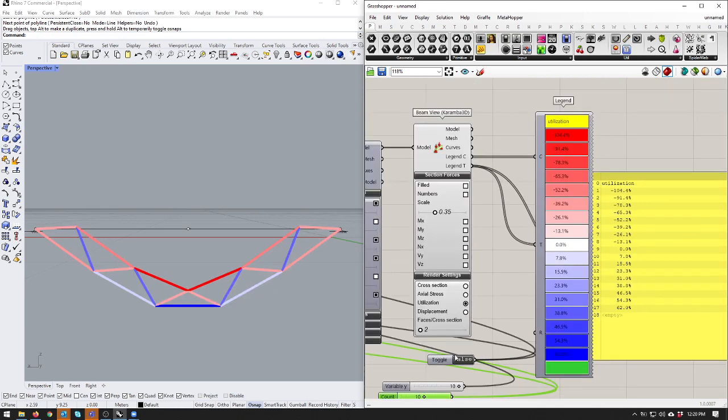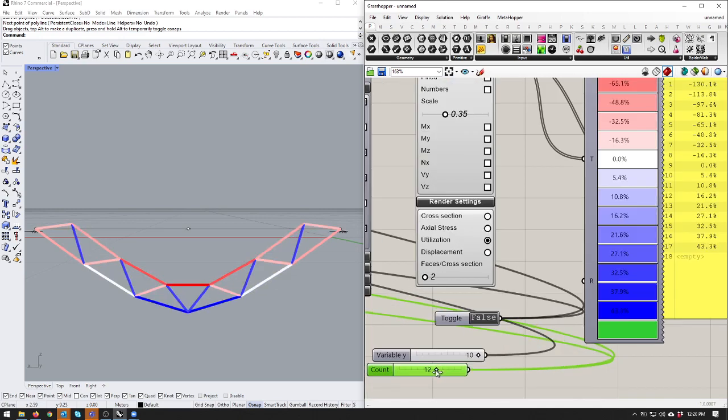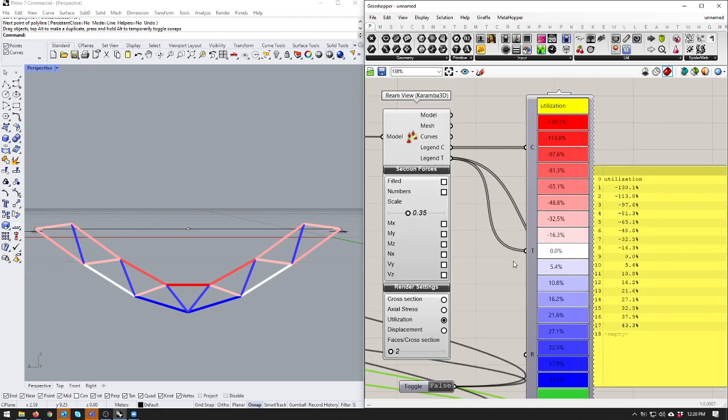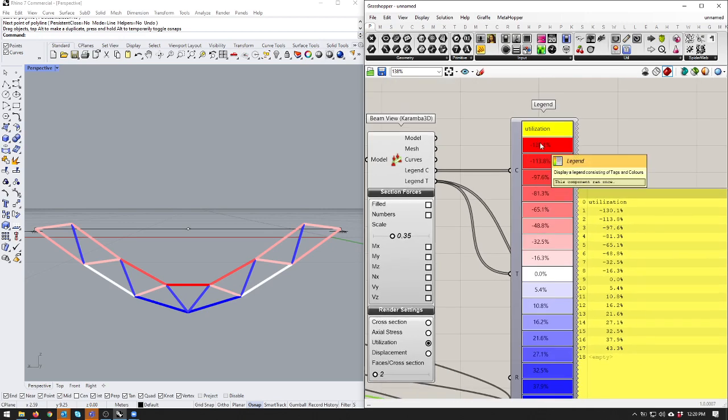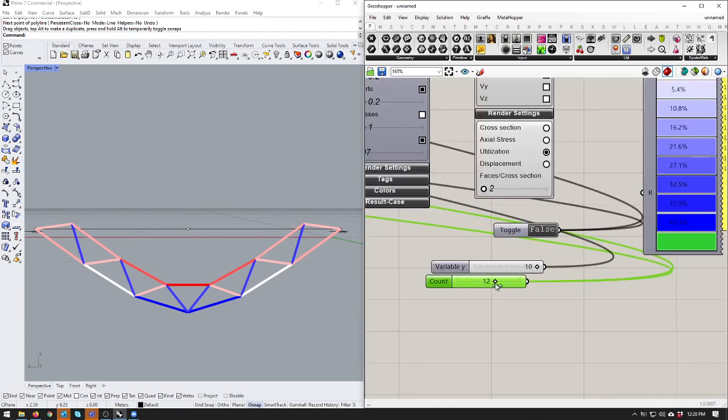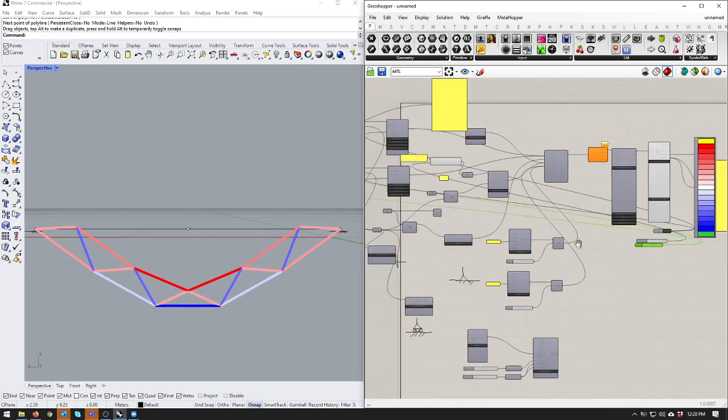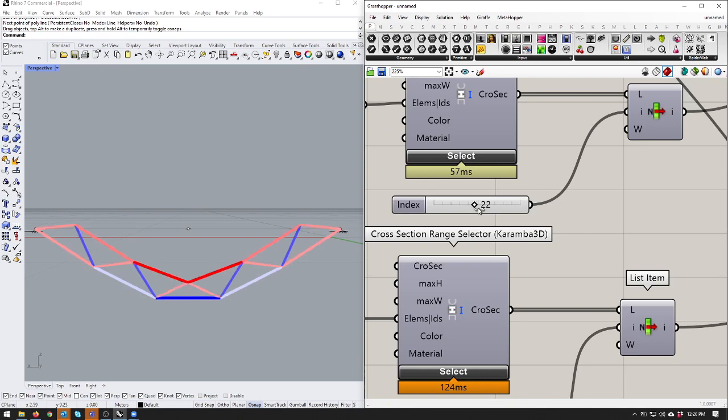I had 10 and it was at 104. Yep. And now I have 12 or 6, and it's now 130. So what's that telling us? It's telling us that the steel is contributing just as much to that problem, the weight of the steel, and adding extra elements is not going to solve it. So what's likely is that we need to start playing with our profiles.